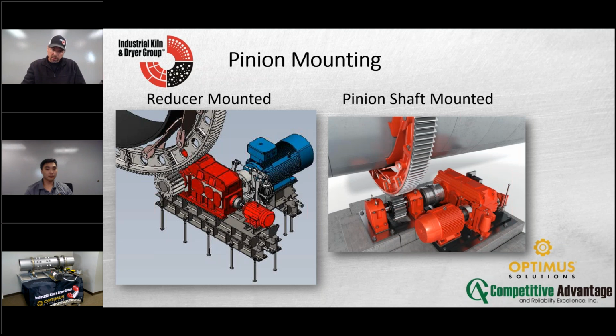Would you say the one with the pinion and shaft and two bearings, is that more for a rigid mount? Yes. You want to make sure everything is shimmed right, aligned right on that spot. You want to make sure your gear run out and your lubrication is good. These aren't the cheapest, especially gear mounted type of systems, compared to maybe a chain drive type of a system, a chain sprocket system. Gears, pinion gear type of systems last a lot longer than chain sprocket types.